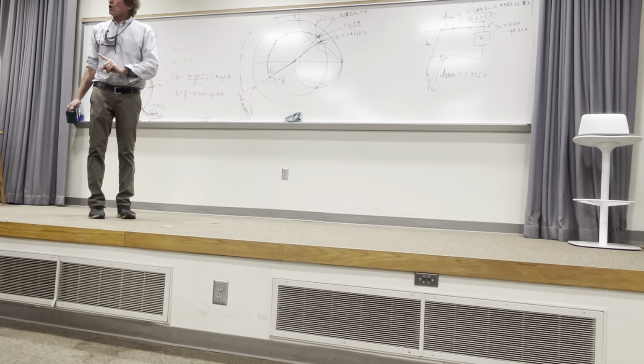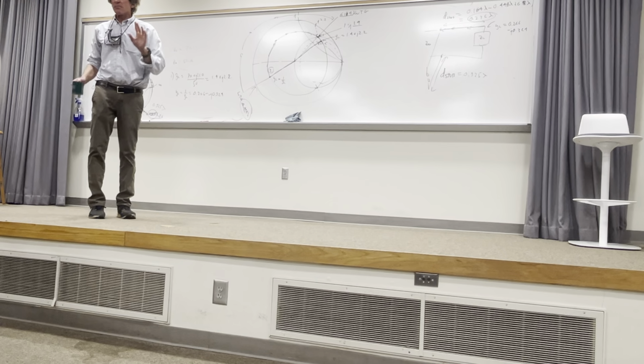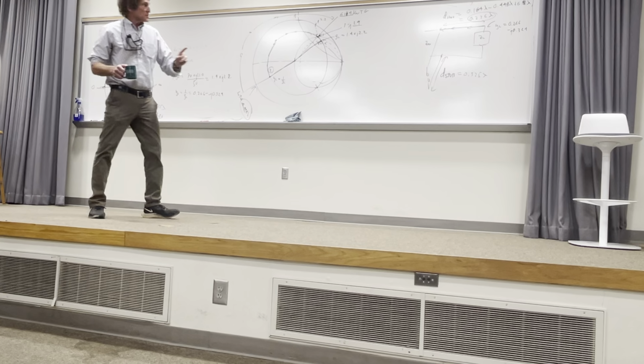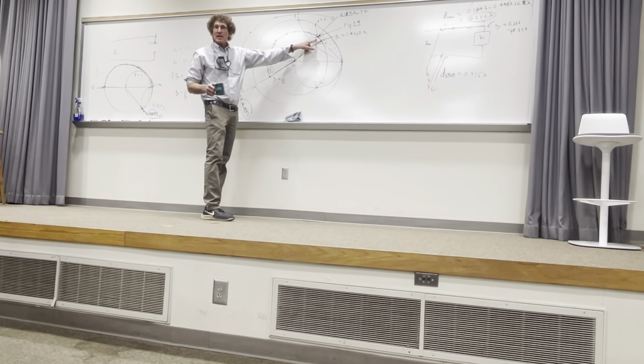Now, instead of an open circuit stub, I'm going to use a short circuit. Exact same problem, only now I want to minimize the length of the through line, using only a short circuit stub. Does this point change where I'm going to attach it? Class? No. Not one bit. If you're minimizing that length, that is the minimum length, period.